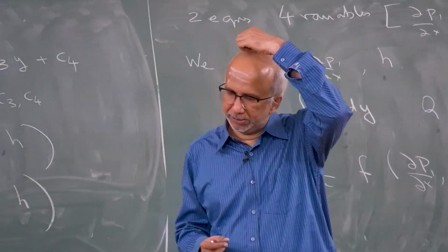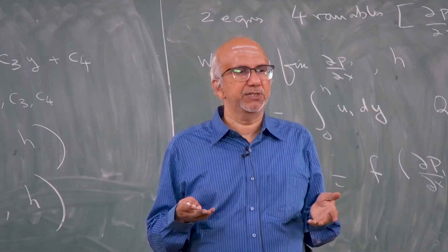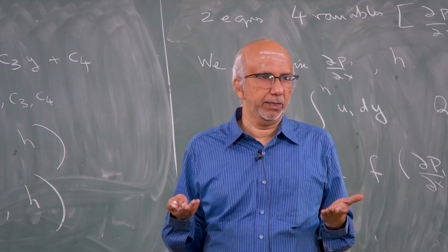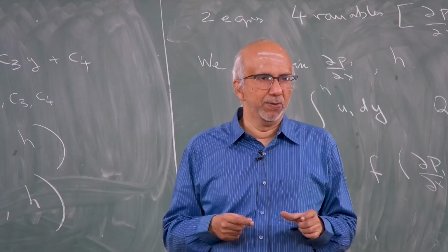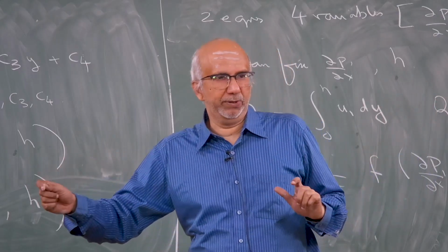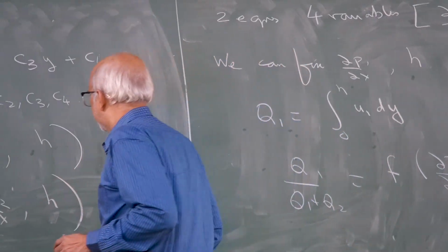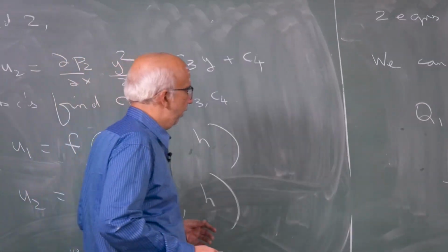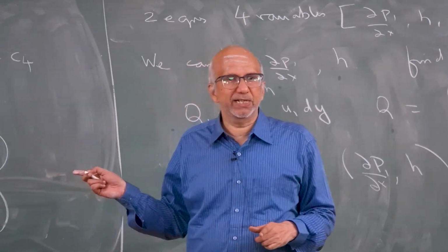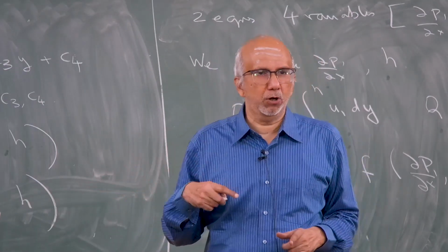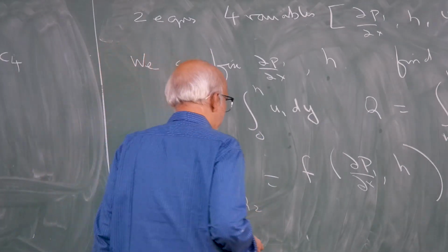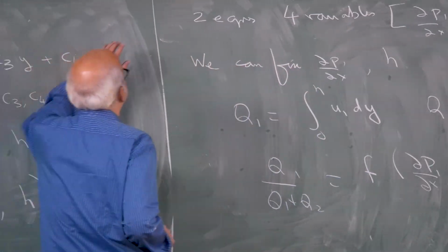So, mathematically speaking, it looks like h is an independent variable, but h is actually a dependent variable. H is not known in an experiment, right. You will experimentally measure the interface position and then you will make a note, for this flow rate fraction I am getting this hold up, for another flow rate ratio I am getting this hold up, okay. So, that is basically what it is, and what I want you to do is do this exercise and plot the flow rate fraction versus the hold up, okay. I want you to do this homework, okay.